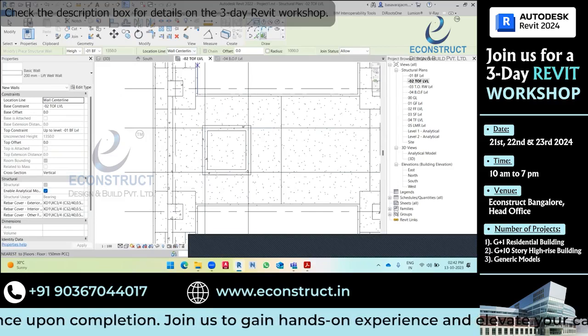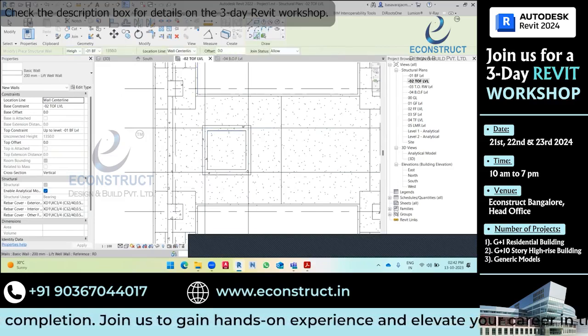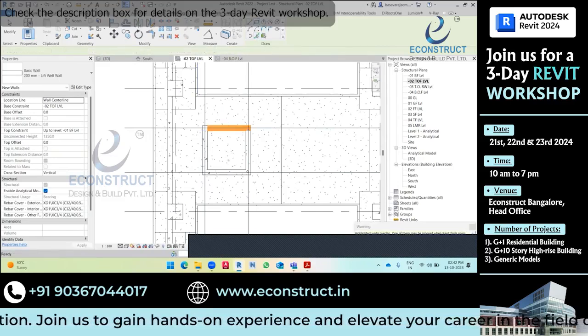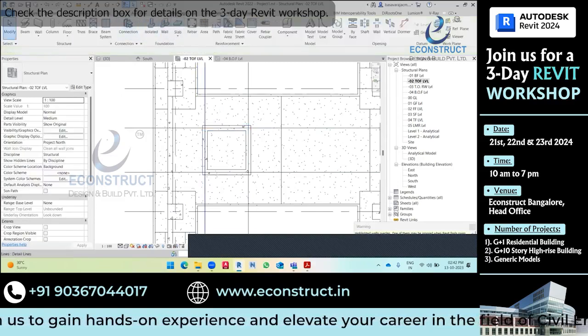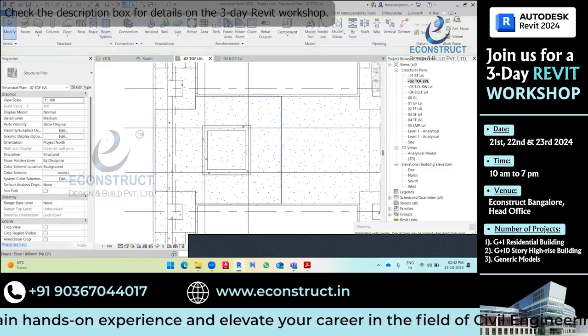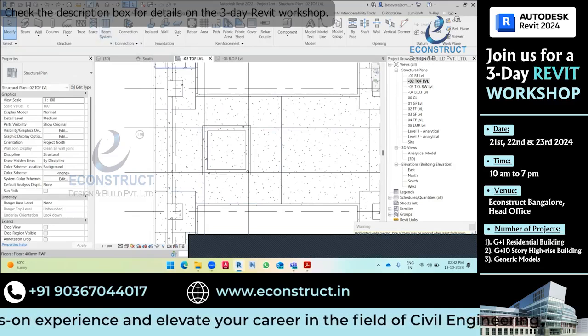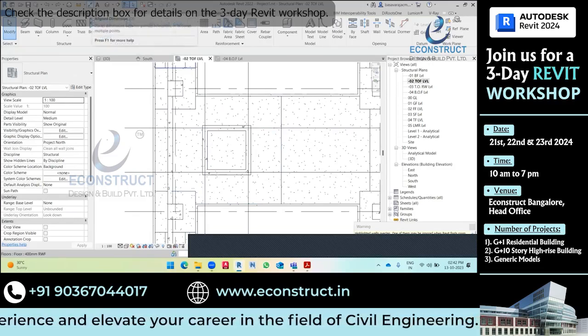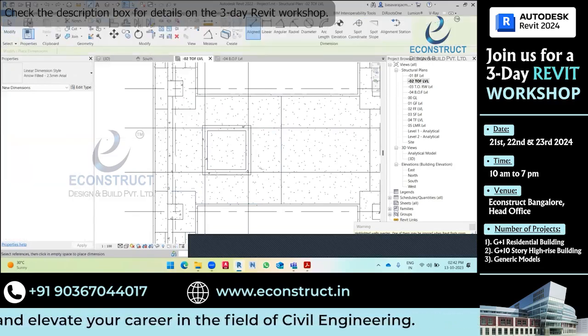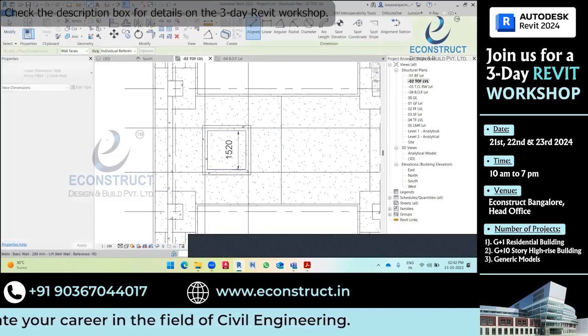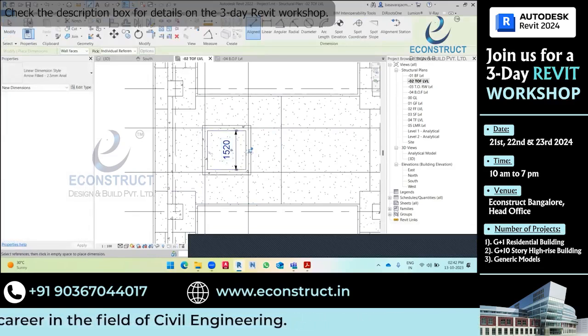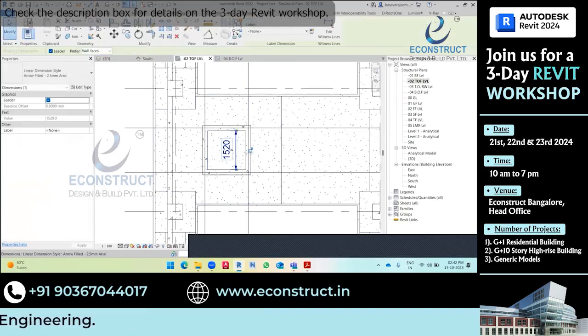Check once how much is the internal dimension. If you want to check the dimensions, in the quick access toolbar, align dimension is there. Select that one, and you can check inner clear to clear 1.52. 1.52 means it is almost 5 feet. So this is correct. Now we have drawn the correct wall.